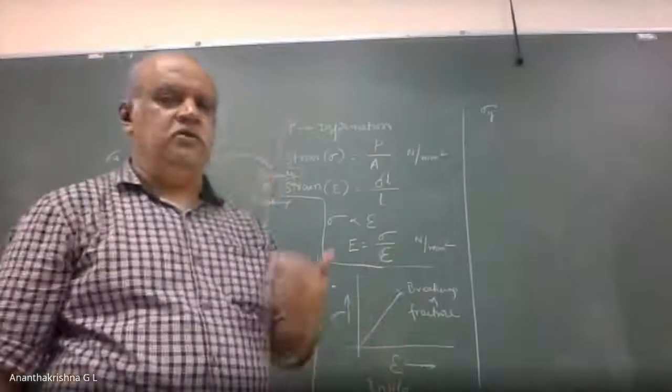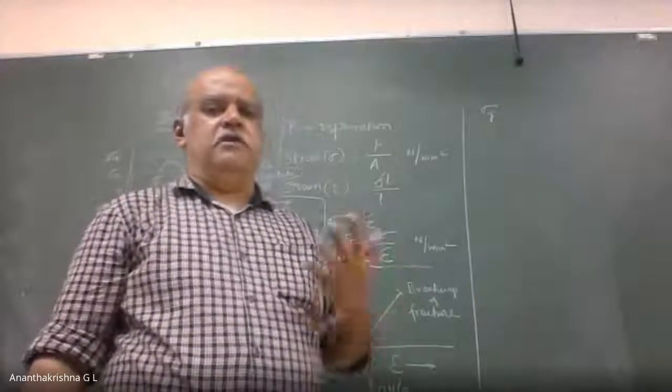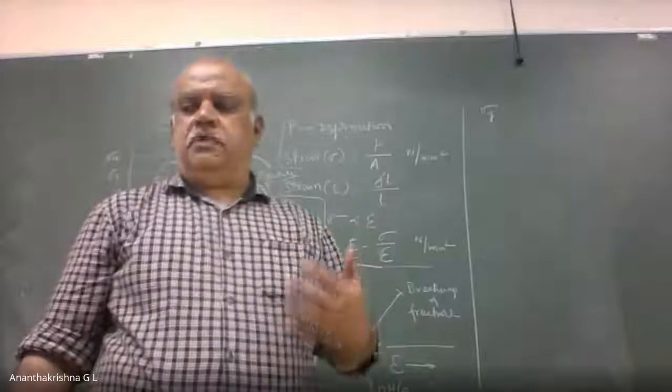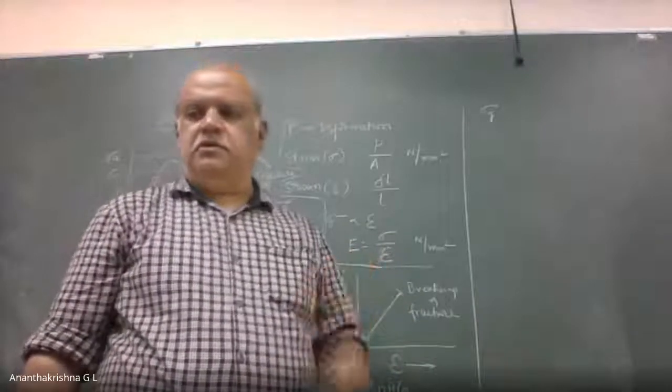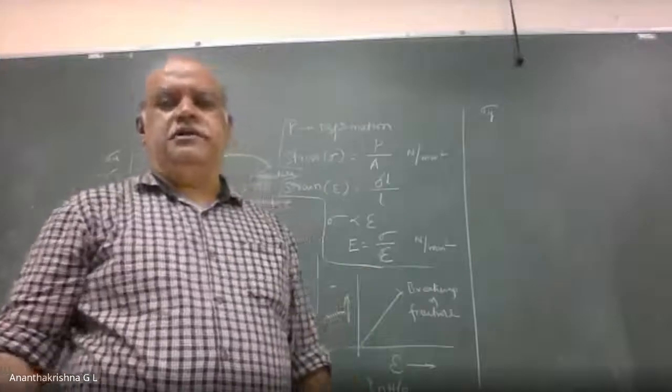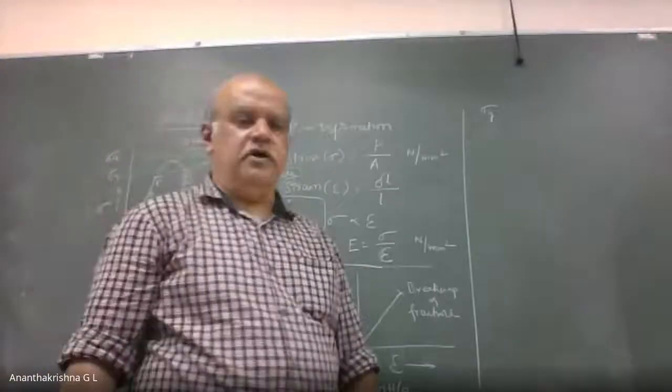Designing in the sense that we are going to determine the size of the component, and the material as well. So for ductile materials, yield stress should be taken as the reference for designing the component.